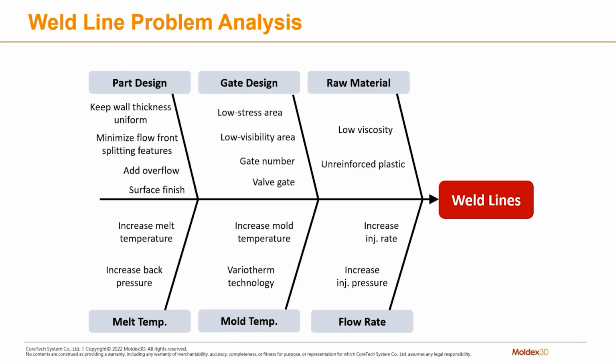So there are various reasons why weld lines get formed. They can be part of the issue in the designing of the part itself. So part design could be a factor, gate design could be another one, raw materials, melt temperature, mold temperature, flow rate, and so on. And then there's a detailed breakdown on this particular slide here.